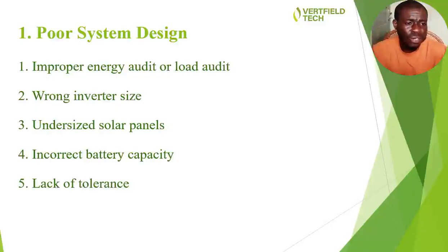In the stage of solar system installations, you do not just get your components, couple them together and do the installation, joining cables together. No, you have to sit down, analyze that system, know where the system is to be installed, do your site survey, do your market survey, do your system design. In doing your system design, you are to take into account energy audit and load audit.